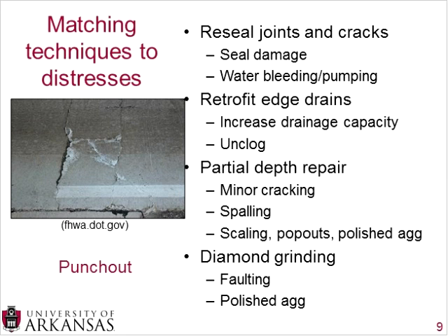Diamond grinding is also a technique in order to restore surface friction. So if you have polished aggregate along your project, you can simply diamond grind along those short sections and restore some of that surface friction.